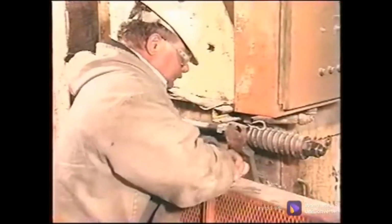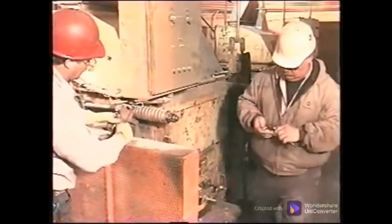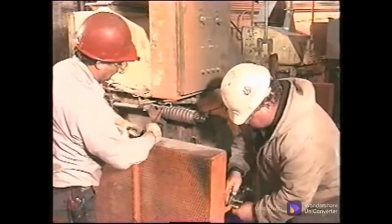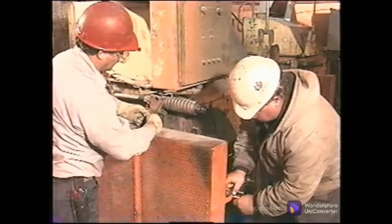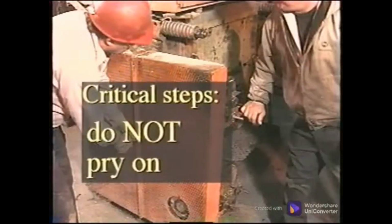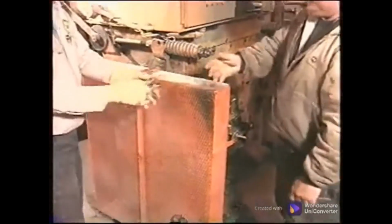However, if the drive runs smoothly and with minimum noise, the sheaves may be in satisfactory shape and may be in alignment. The critical steps were performed. All the belts were replaced with a matched set. They were installed without damaging the outside wrap, the internal fibers, or the reinforcing cord, because they were not pried onto the drive, and the proper tension was set. Hopefully, this set of belts will reach the design life of 25,000 hours.